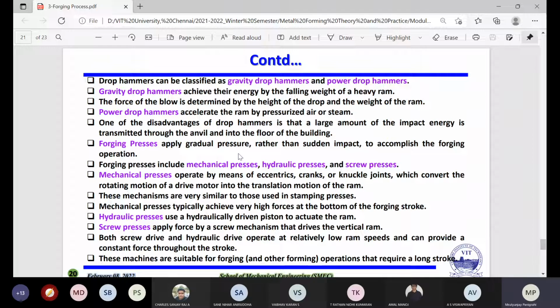But there are some furnaces, and I'm not saying this applies everywhere. For example, a laser heat treatment furnace. If in that furnace you increase or decrease the temperature at a slow rate, maybe 2 or 3 degrees C per minute, the equipment will be damaged immediately. So in that furnace you have to increase the temperature at 50 degrees C per minute minimum, or maybe 100 degrees C per minute. I remember when I was doing this kind of work, to reach 1000 degrees C within 3 or 5 minutes, then this furnace will work well.